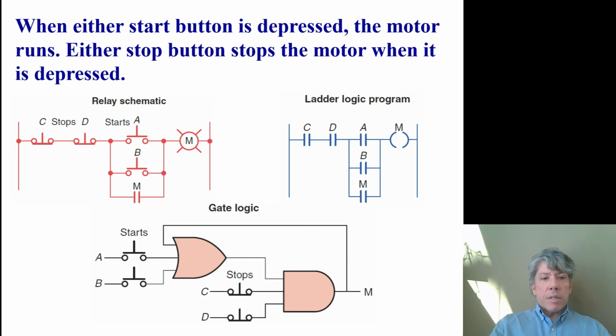So you can see how it's set up, where we've got a tri-input OR gate so that the output can feed back to the input. We've got switch A as one of the inputs to the OR gate, switch B as one of the inputs, and if any one of those signals is true, then the output from that first OR gate is true, the result of which goes into a tri-input AND gate.